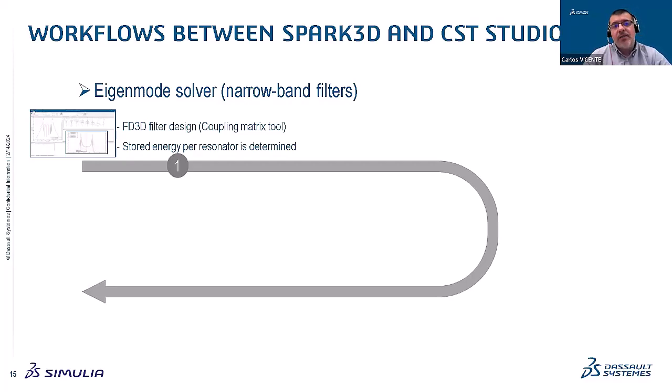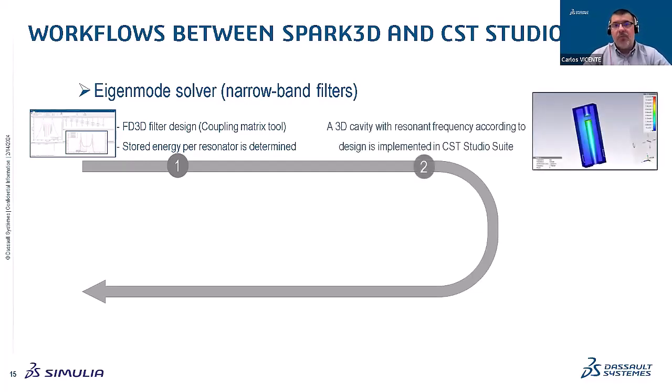And that stored energy is the key here because it relates the breakdown field in the isolated cavity with the breakdown field once that cavity is integrated into that particular filter. Okay, so after that, typically what you do is to design the cavity. This is the typical procedure for filter design. You would design a cavity resonating at the frequency needed with the Q factor that you need and so on. And once you have done that, you can export the fields of this closed isolated cavity to Spark 3D.